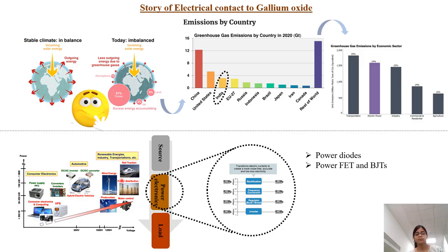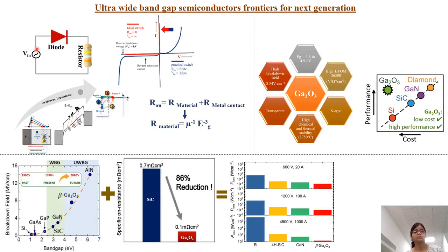For all these applications, the major portion is the power electronic circuit, which consists of rectifiers and converters. These rectifiers and converters consist of a special arrangement of diodes, FETs and BJTs in switching mode. So let us consider a simplified diode circuit. These are the output characteristics of a circuit in which I have compared the practical one with the ideal one.